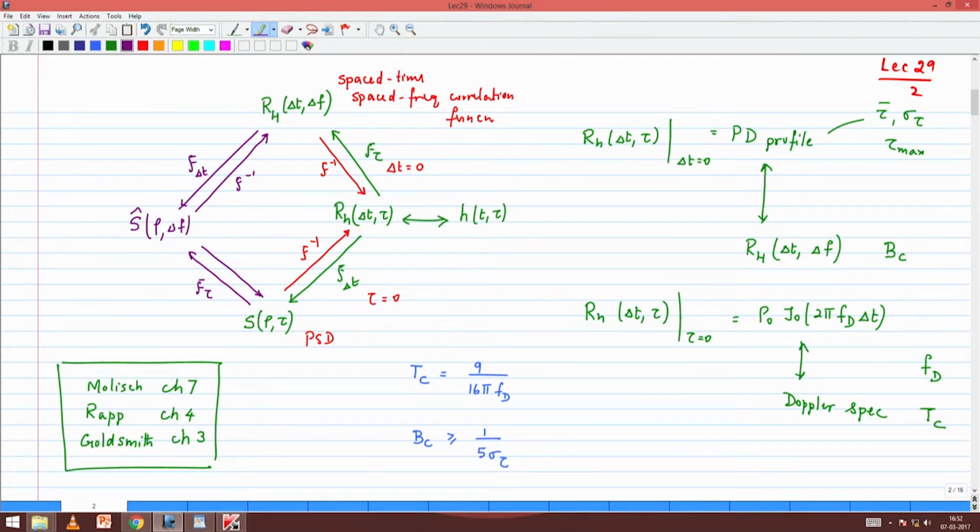If you want to do frequency hopping, you want to make sure that your frequency hops are greater than coherence bandwidth, and your channel estimates are done at a time period which is less than coherence time. So basically you make sure that you are estimating the channel as it changes.